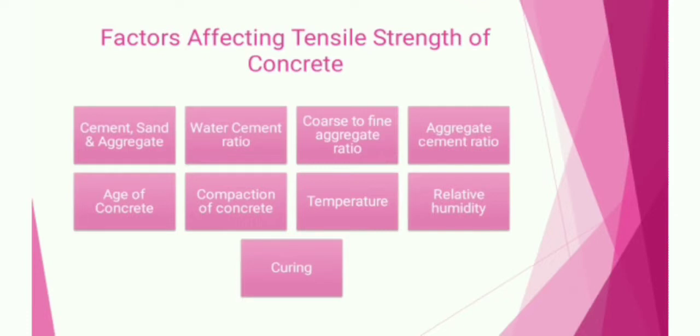Water-cement ratio. The higher the water-cement ratio, the greater the initial spacing between the cement grains and the greater the volume of residual voids not filled by hydration products.